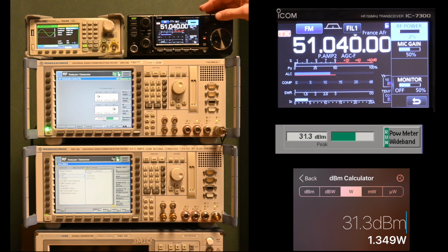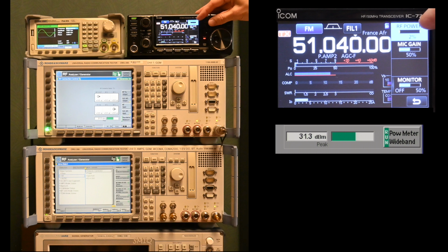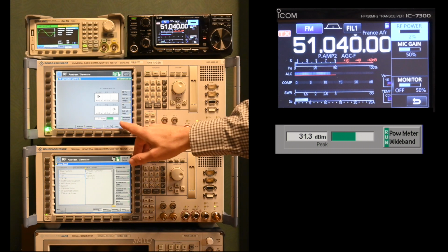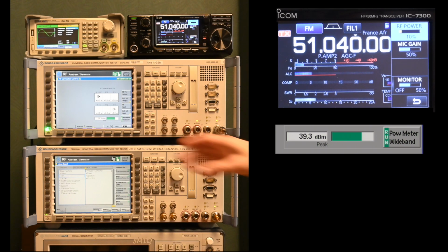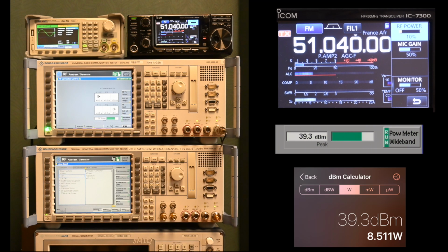And then we should be able to bring it up and see what higher power levels, because as is already suggested here by the little bar, there's still some margin to go up in power. So let's see if we turn this to 10% of its transmit power. We're at 39.3 dBm, which is 8.5 watts of power, I believe. Slightly under the 10 watts, 10% of 100 watts, but again, this is probably not very precisely calibrated.